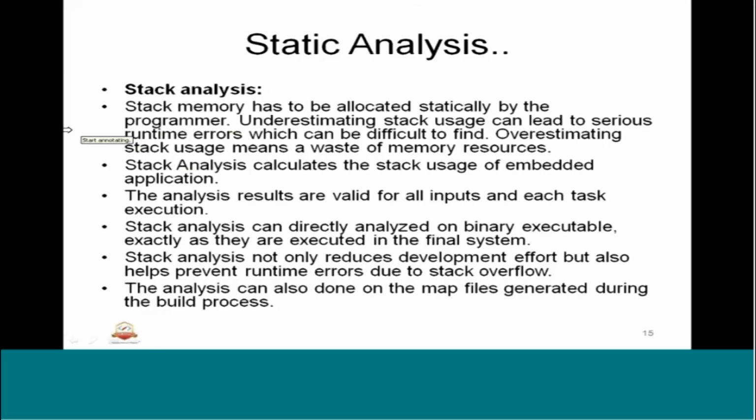So underestimating stack usage can lead to serious runtime issues. Program behavior can be unpredictable when there is a stack issue, and which is very difficult to find. Similarly, overestimating a stack usage also we cannot have. We cannot have a 200% or 300% stack usage buffer or allocation, because we are wasting the memory.